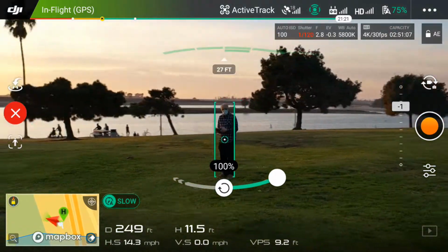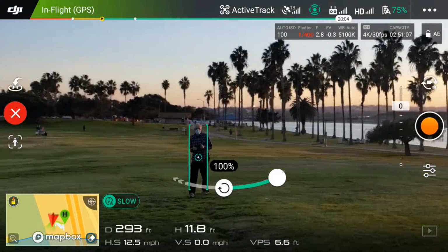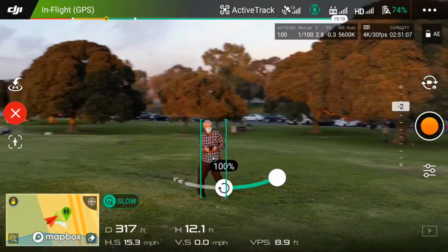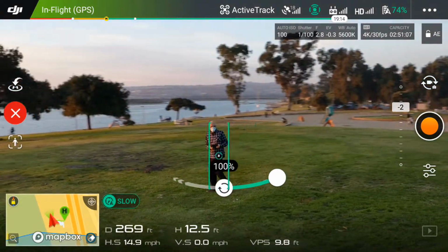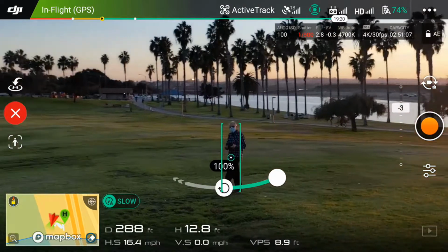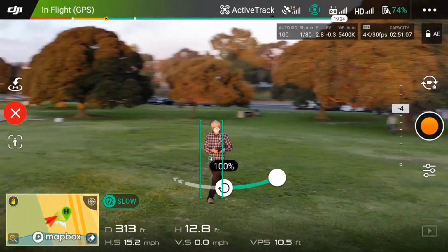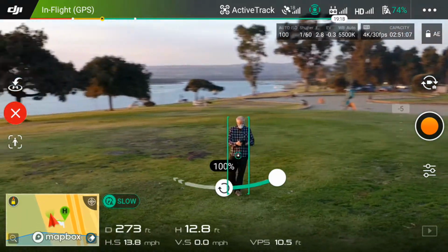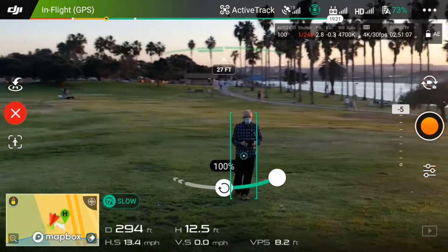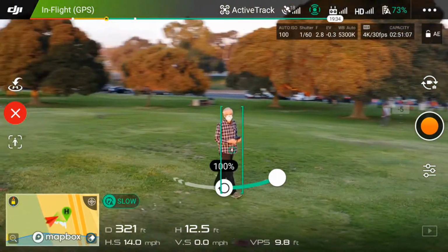However, when I make a circular rotation in a slope area, when the land is a slope, the circular rotation will be at a constant height based on GPS signals, not the ground. Meaning, as the drone gets to the higher level, it gets closer to the ground. As the drone gets to the lower level of the slope, it gets further away from the ground. So the drone is keeping its altitude constant, regardless of the ground beneath it.